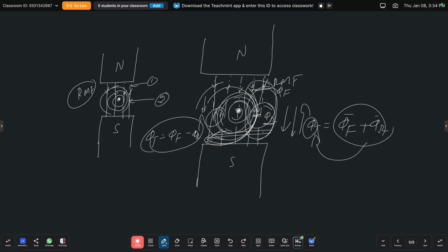So the 3-phase induction motor is a self-starting motor. As per Faraday's laws of electromagnetic induction, two fluxes will be produced. Through the interaction of these two fluxes, torque is produced in the rotor. Due to the torque, the rotor starts to rotate continuously. Now this rotor tries to get to the rotating magnetic field speed.